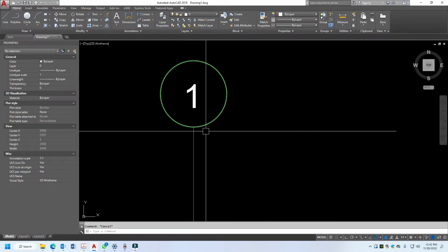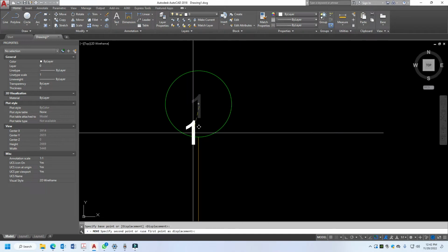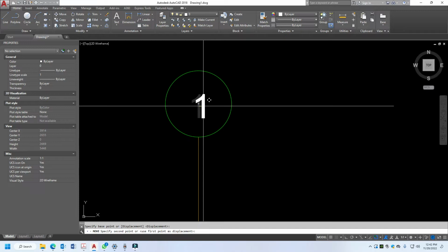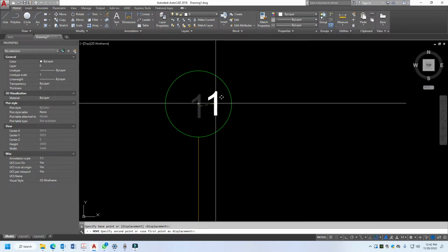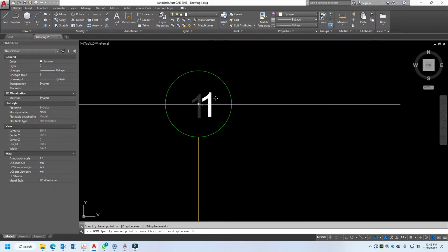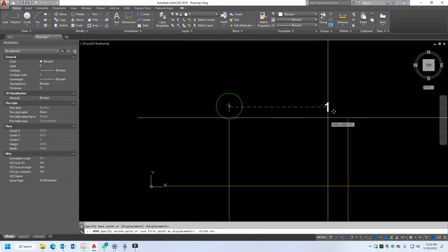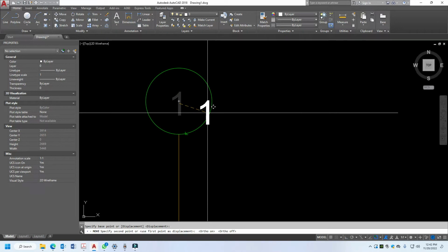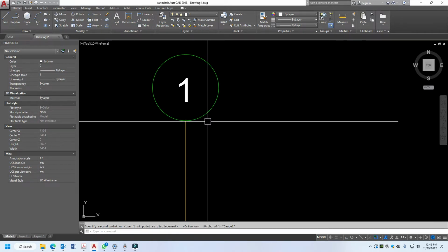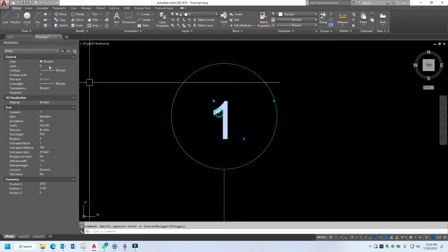When moving, just type M, then click, space again, then click, then you can move. If you want to make it a straight move, while clicking the item, just click F8. So it's straight. If you don't want it like this, just turn off F8. Then escape is always an exit or cancel. So layer 1 is 0, set to 0. You need to set it to grid and make it green.